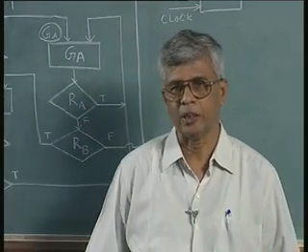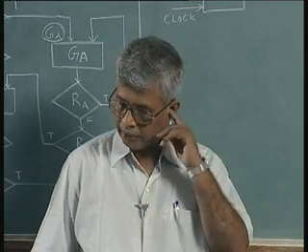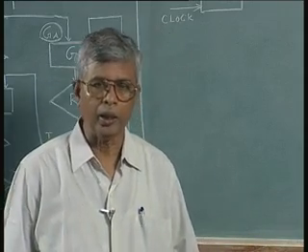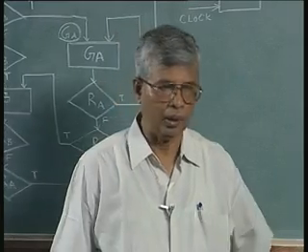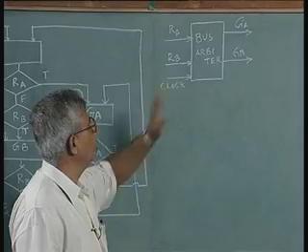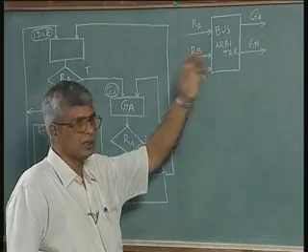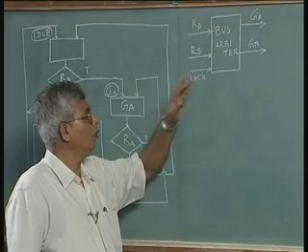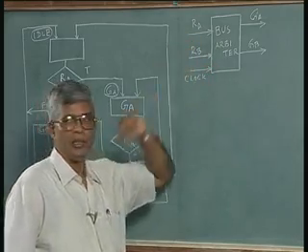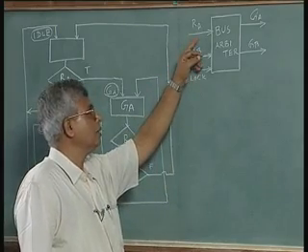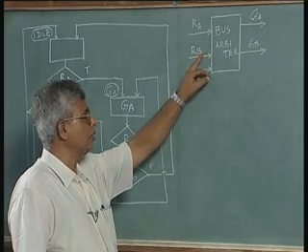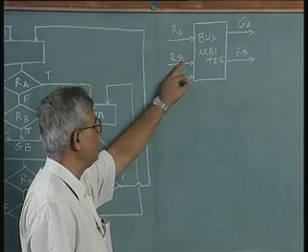ASM stands for algorithmic state machine, and we set about to start the design process with a simple example of this bus arbiter, wherein there is a bus which is available, which will be requested by two units called A and B. So, whenever the unit A requires the bus, it gives an RA signal as input to the bus arbiter, and whenever system B requires the bus, it gives a signal RB.